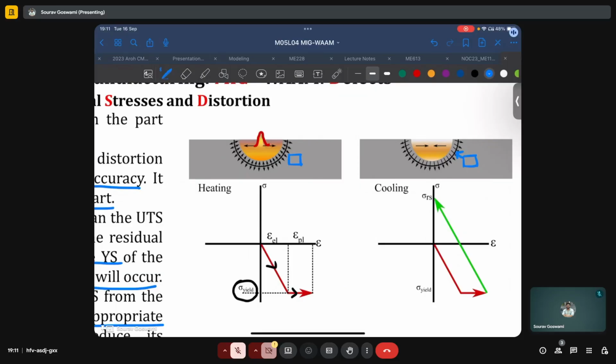And this tensile loading will happen parallel with the compressive loading which is experienced before because the Young's modulus of the material will be the same. And now, when all the deformation has gone, there is this residual stress in the material, which is of a tensile nature.